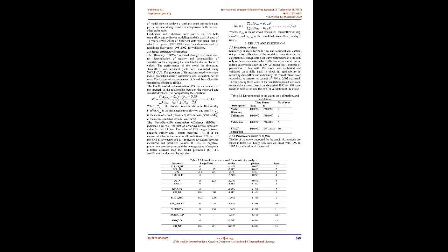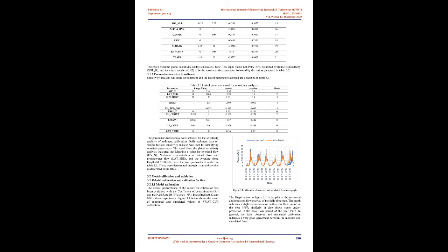2.8 Model Efficiency Evaluation. The efficiency of SWAT is tested through statistical tools for determination of quality and dependability of simulations, comparing the simulated values to observed values. The performance of the model in simulating stream flow and sediment yield was evaluated using SWAT-CUP. The goodness of fit measures used to evaluate model prediction during the calibration and validation periods were the coefficient of determination, R2, and the Nash-Sutcliffe simulation efficiency, ENS.